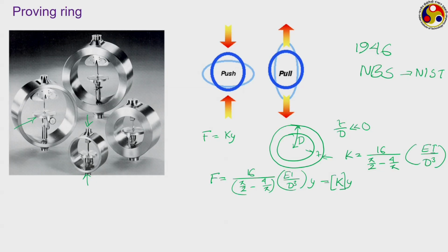Sometimes instead of measuring this way, we go for the measurement of the angle of deflection. That is, if this is the original shape, I am trying to draw a circle actually, but it is ending up with quite an odd shape. Let us assume this is the initial shape. So, these are the primary dimensions. Now, if there is a deflection of this one and the deflection is measured in terms of an angle phi, then the corresponding bending moment can be related as M equal to PR by 2 into (cos phi minus 2 upon pi), where R is the radius of this particular circle, the initial radius, P is the, oh sorry, I have written both to be R, it should be P. P is the pressure that is acting on this, and M is the corresponding bending moment. From there also we can easily calculate the deflection just by measurement of the value of this phi.